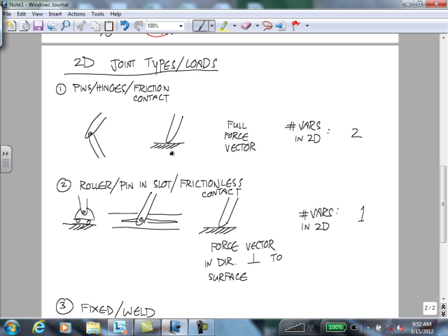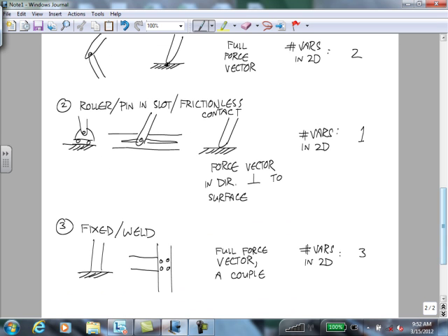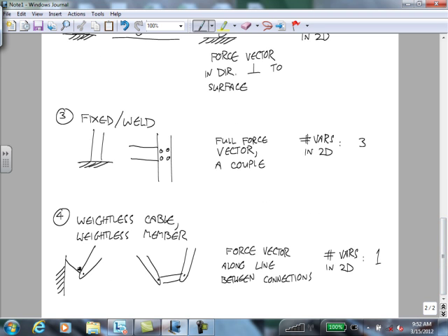In the free body diagram for member 2, you'll have a force vector on 2 by 1, and then you can reduce those variables as negative F12. Okay. So when you're solving a linkage, in this case, those are going to be variables you're going to have to solve for, and that's more constraint equations that you're going to have to come up with. Okay.